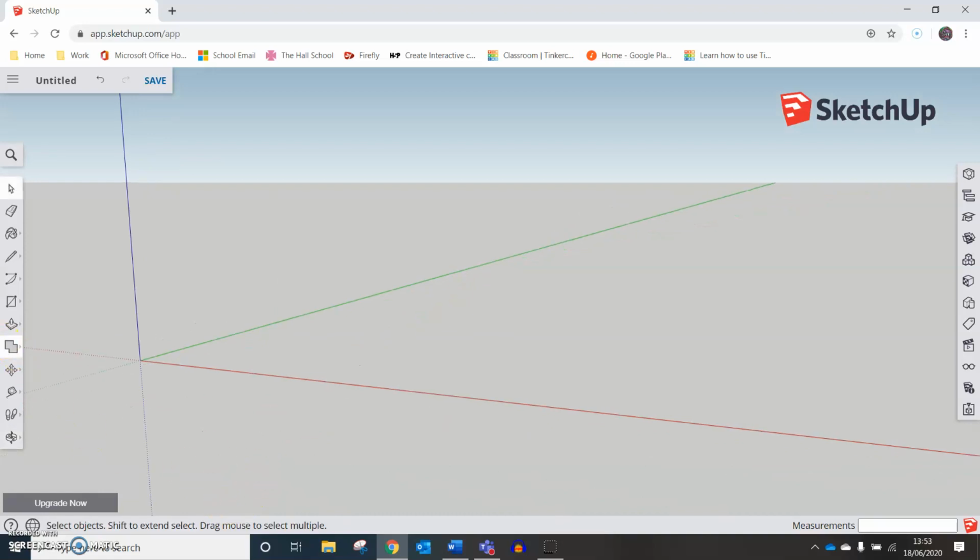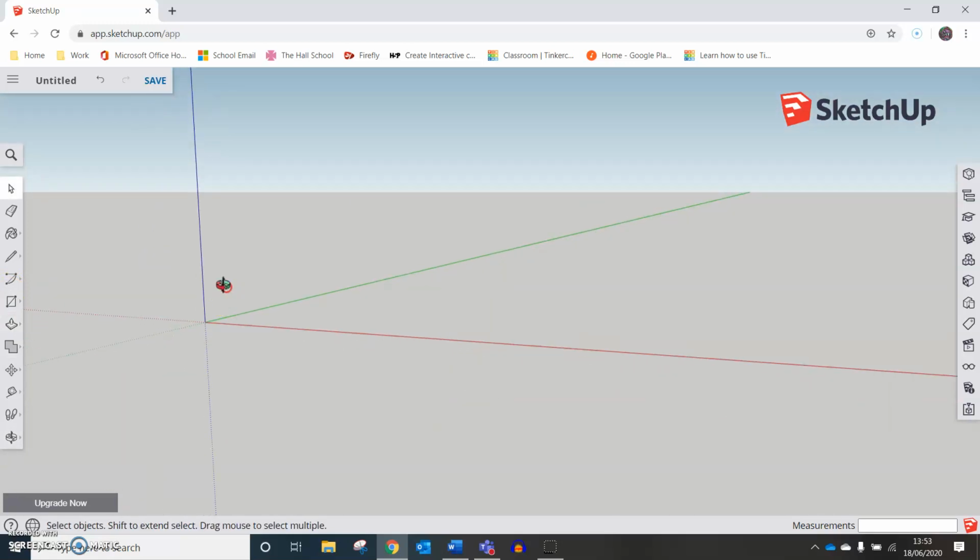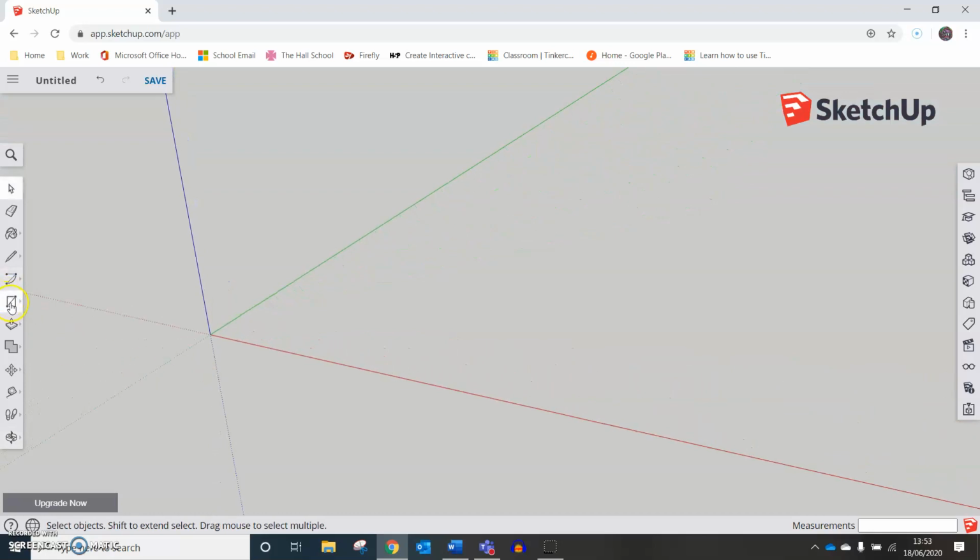Okay. I'm going to start by drawing some shapes. So I'm straight into drawing, just move out a little bit and look from above slightly. And I'm going to click the rectangle tool. When I click on the tool, you'll see that various other tools appear that I can use, but I'm going to start with a rectangle. I haven't dropped, so I'm just going to click, drag, and then type 1000 x 1000, 1000 by 1000, and hit enter. And drop.